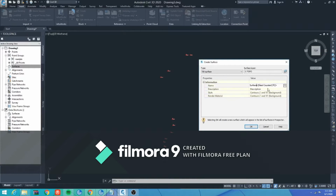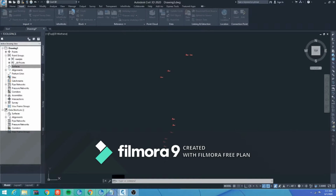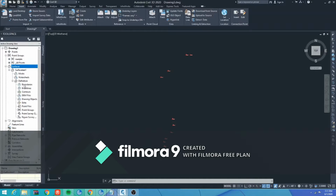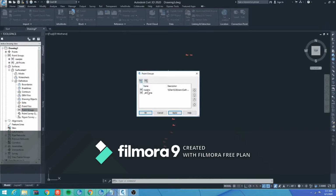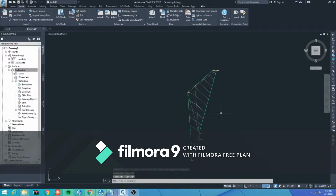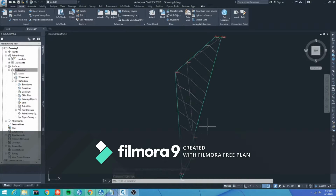So now I'm going to name my surface. Hit OK. And surfaces need points so that I can create an area. So I'm going to go on Surfaces, Definition, and I'll insert my point group into the surface. I'm going to add my road points here. Hit OK. So we have created our surface, but what happens if we want to change how it's viewed or looked at?